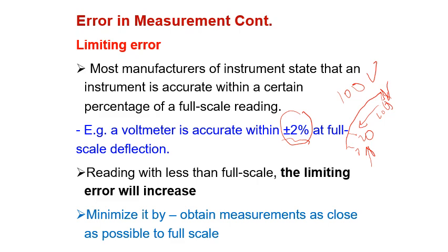So how do we minimize this kind of error? By measuring a value which is close to the full scale.